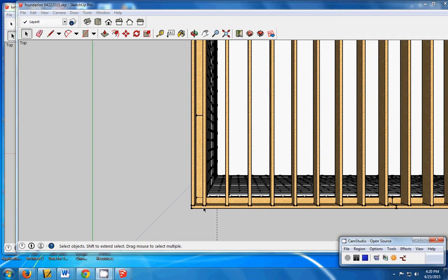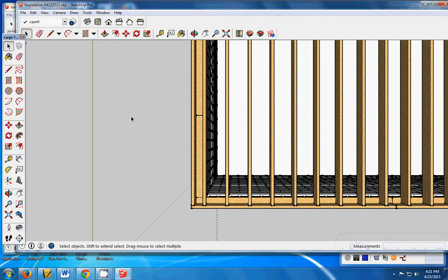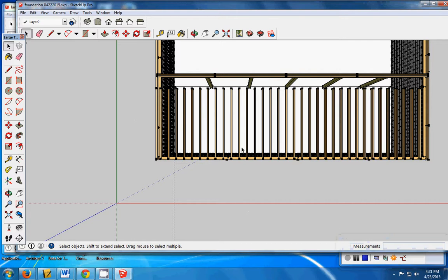When I got to the far end, I found that I needed to position one more floor joist, but there would not be 14 inches between that and the header joist on the other side. That's okay. It's better to have a shorter span than a longer span. So now I have that row of floor joists in place. They're not quite long enough to reach my center.